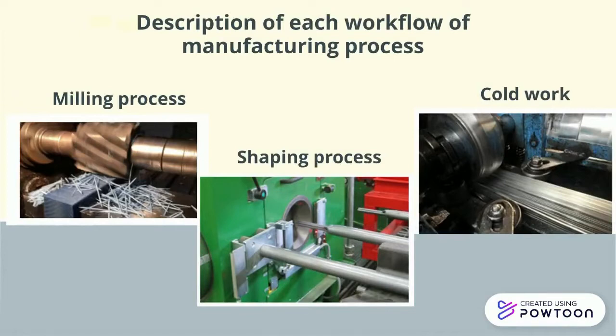Shaping process. Tube drawing is the technique of decreasing a big diameter tube into a smaller diameter tube by drawing the tube through a die. This method yields high-quality tubing with accurate dimensions, a smooth surface finish, and the extra strength of cold working. As for the hypodermic needle, the tube drawing will produce a mass of 0.0011 kilograms and 0.5 millimeters cross-section.